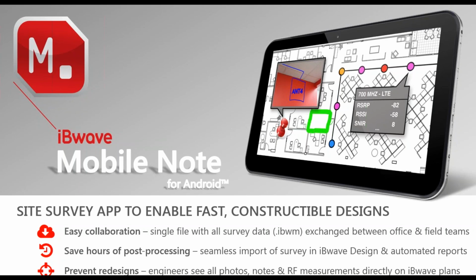In short, it is an Android app that basically helps capture and, most importantly, centralize all the survey data inside a single file, which we call iBwm. This file can then be imported inside iBwave Design or even the free iBwave Viewer, allowing you to see all your photos, notes, and RF measurements directly on your iBwave plans. If requested by the carrier, from there you can also generate some site survey reports that are available, such as the photo location or measurement plots for the KPIs, and even export all your pictures if you'd like to.